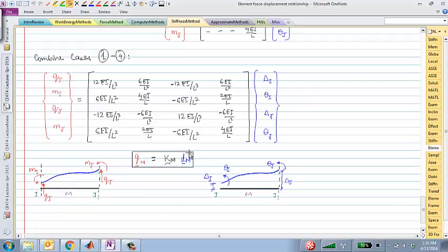And I pointed out that this is the same relationship that we had for the truss elements, which was extremely simple because the truss element response depends only on the change in length of the element. That was the +1, -1, -1, +1, a very simple 4x4 relationship. That relationship never changes. But in this case, all of them are non-zero. For the truss element problem, you had only 4 entries which were non-zero. Here, for the beam element, everything is non-zero. So that's where we were about last time.